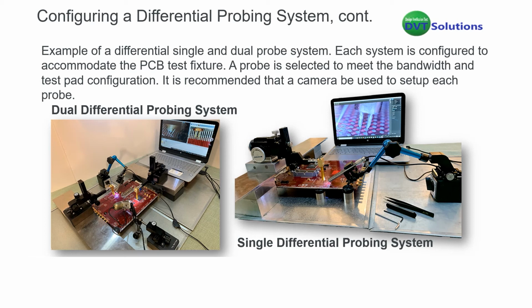It raises it up high enough that I could slide the board underneath. That allows us to probe anywhere into that board that's necessary, because primarily the length of the arm of the manipulator is about 5 inches. So if you brought that manipulator right up to the edge of the board, you're only going to be able to probe into it about 5 inches. So if your board is, say, wider than 5 inches or 10 inches, then you might want to take a look at getting a probe bridge to assist the probing of it.